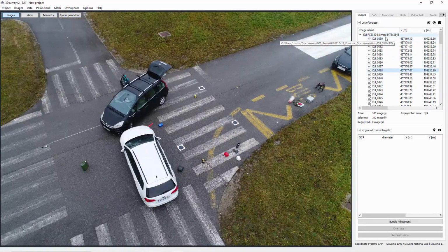I didn't mention before about the orientation. Now here is a nice image where you can see three 3D Survey targets which were placed perpendicular to each other, and the distance between them was 3 meters. In this way we generate a so-called local coordinate system, and we generate our ground control point file with the local coordinates. In this case, we don't need GNSS or GPS instruments, which can be quite expensive, from 5 to 10,000 euros.